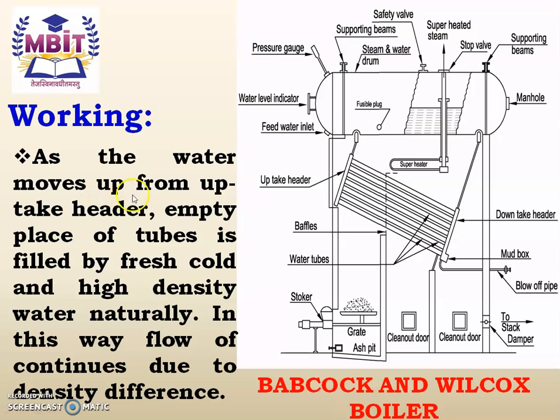As the water moves up from the uptake header, the empty place in the tube is filled by fresh, cold, high density water naturally. In this way, the flow of water continues due to the density difference.